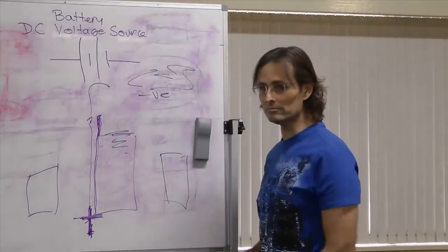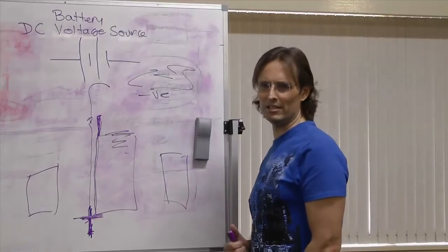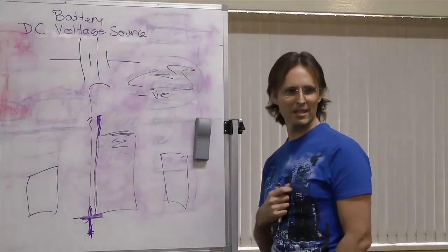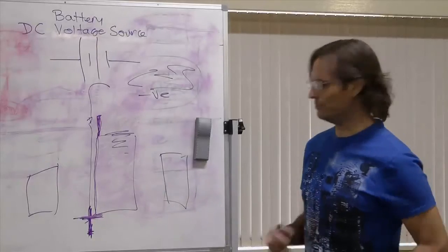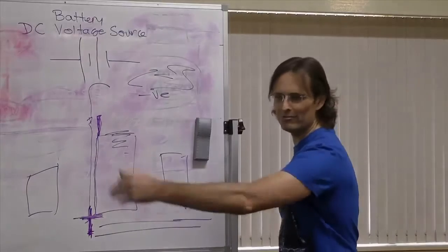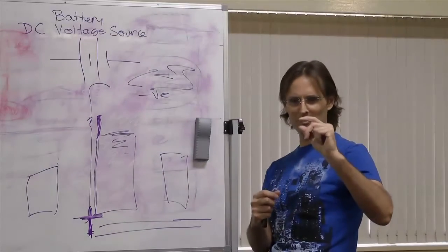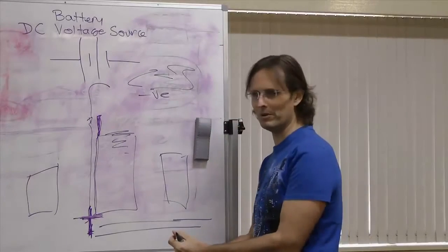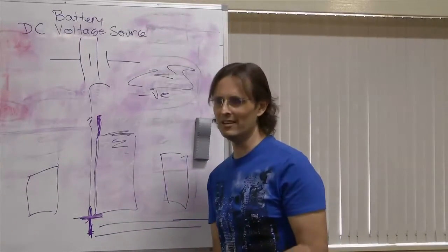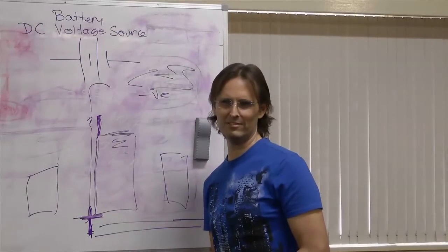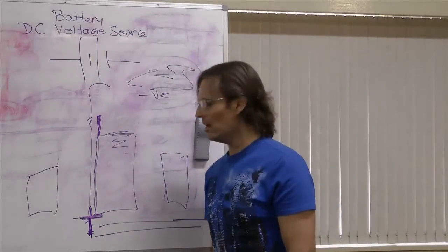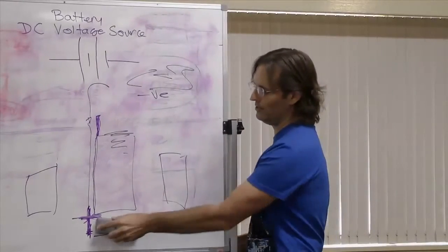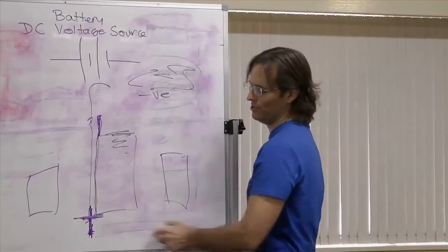And is it like a big metal thing, or what is it? Yes, it's usually a highly conductive metal that's actually dug into the ground. Sometimes they connect it to the water pipes because the water pipes are metal that run through the ground. Exactly. The beauty of connecting it to a metal water pipe is the pipe might run over kilometres, and usually the thickness of the pipe is very high, so it can carry very high amounts of current. And because it's dissipated over a system, if it's a copper pipe buried under the ground, then you'll dissipate the energy very rapidly. Does that make sense? Yeah, they stopped using that practice after a while because there are earth faults and leaks in the house and people getting tingles off the taps. Exactly. They used to do that a lot, but nowadays they try and do it so that each house is isolated.